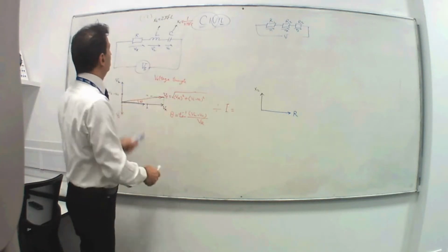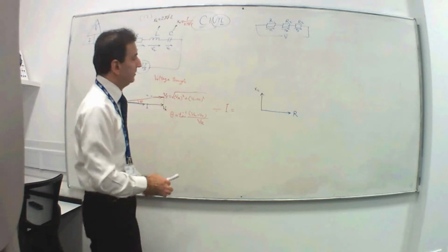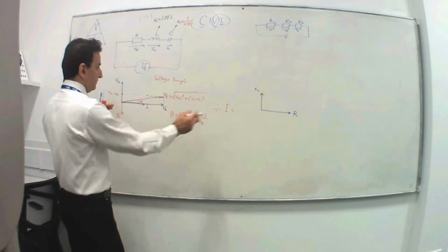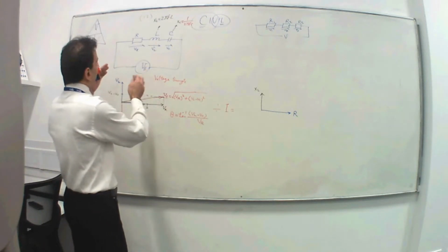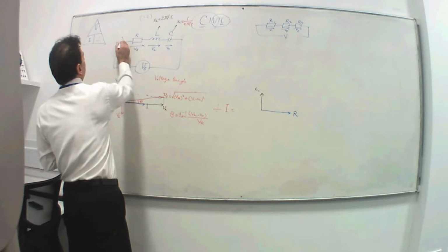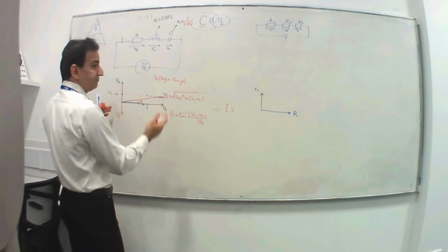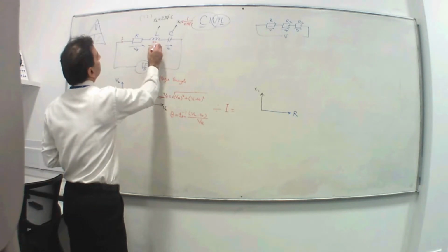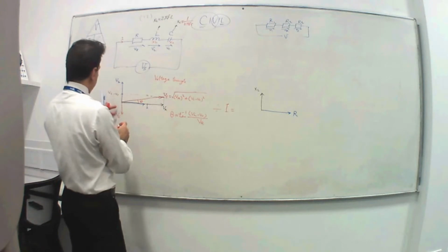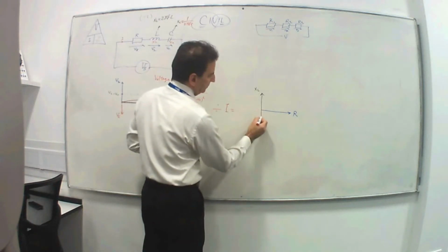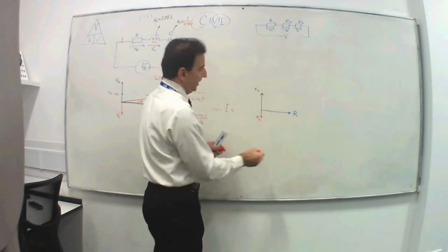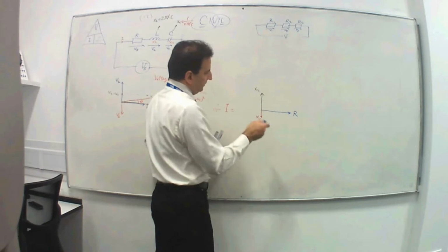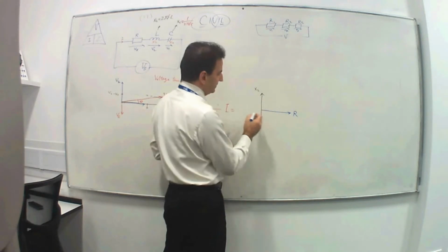And that's the first thing you do. Any circuit you see, immediately convert that to XL and XC. Then VL divided by I, which is going through all the circuit, I is constant, gives you XL, and VC divided by I will give you XC. Now, if you get the overall resultant of this phasor diagram, you'll find Z, or impedance.